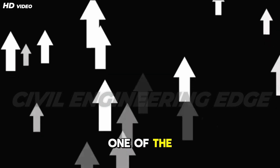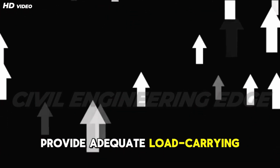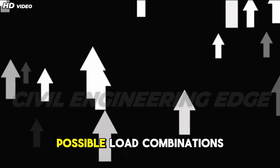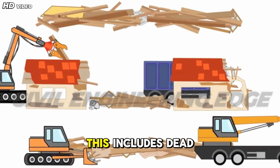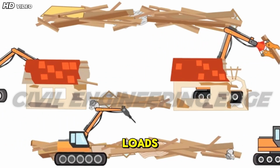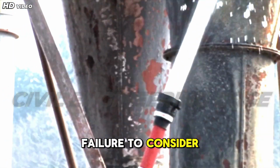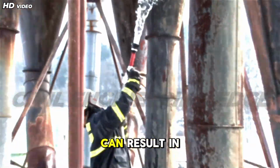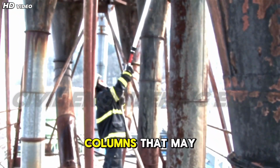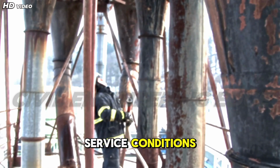One of the primary goals of column design is to provide adequate load carrying capacity under all possible load combinations. This includes dead loads, live loads, wind loads, seismic forces, and accidental loads. Failure to consider these load combinations can result in underdesigned columns that may crack, buckle, or collapse under service conditions.